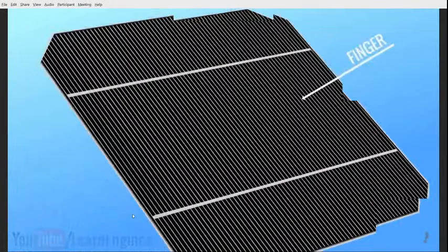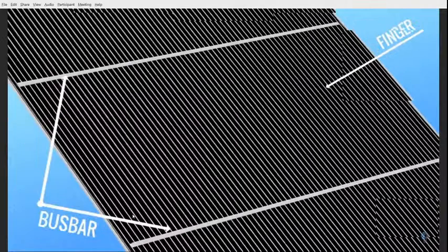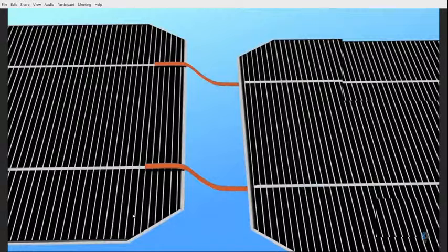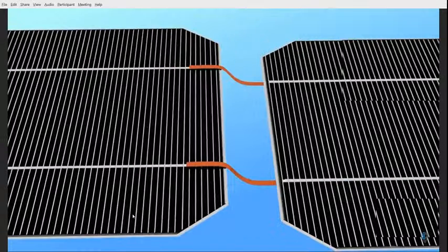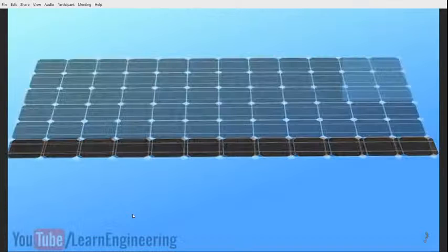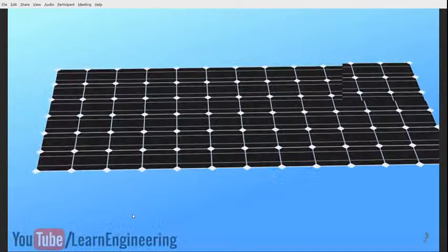Fingers, the electrons get collected in four spots. The top negative side of this cell is connected to the back side of the next cell through copper strips. Here, it forms a series connection. When you connect these series connected cells parallel to another cell series, you get the solar panel.